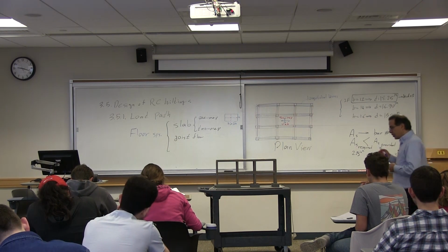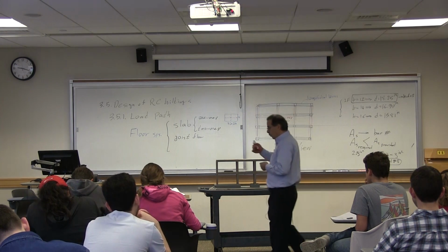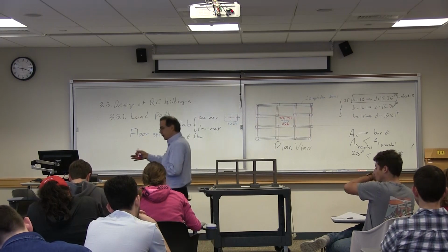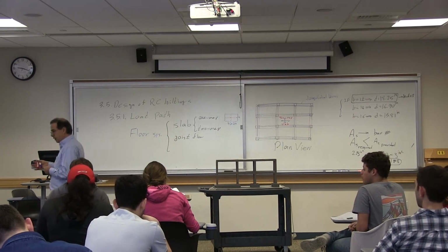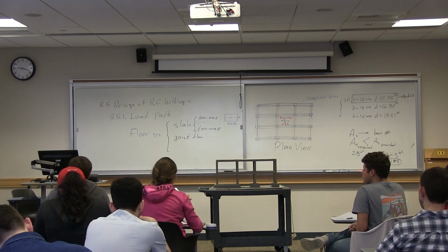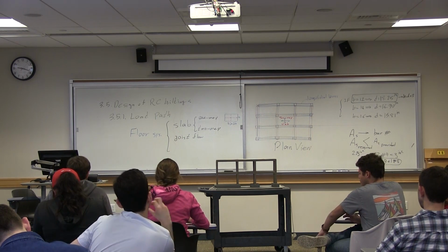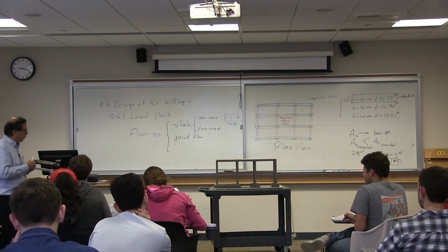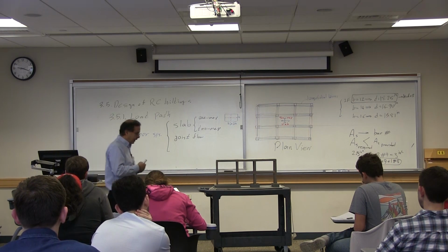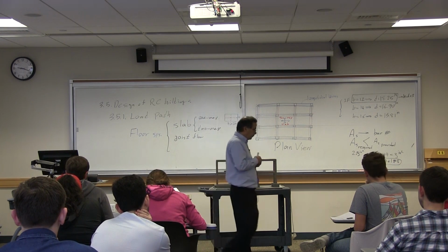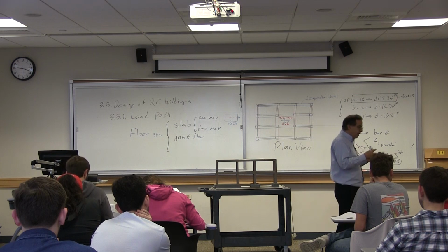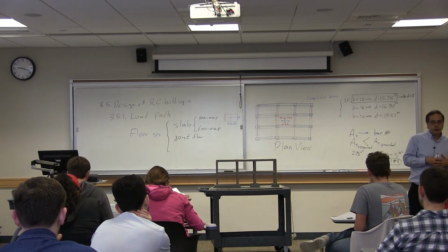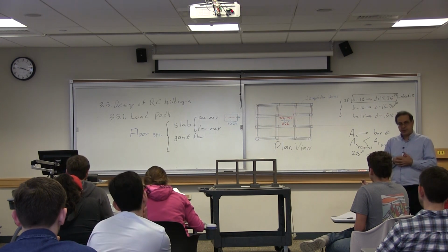So, which direction does the load go through more? The direction that is stiffer. Why? Because the deflection in two directions is equal, and a stiffer beam would need more load to deflect the same amount. These were qualitative evaluations of what happens.